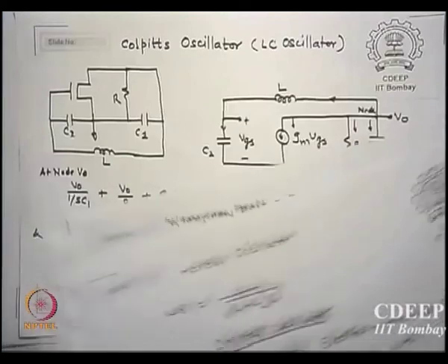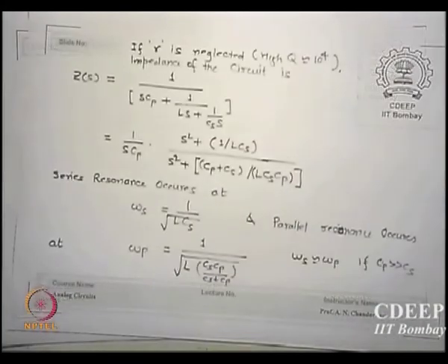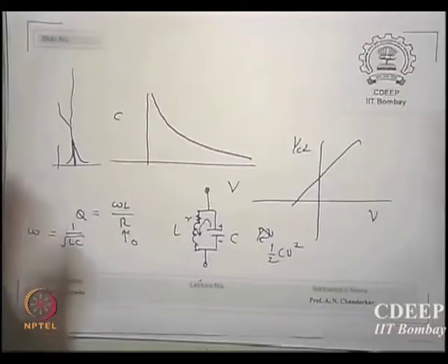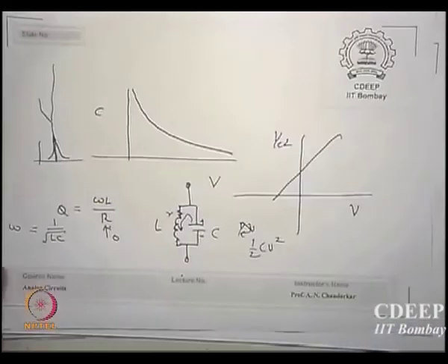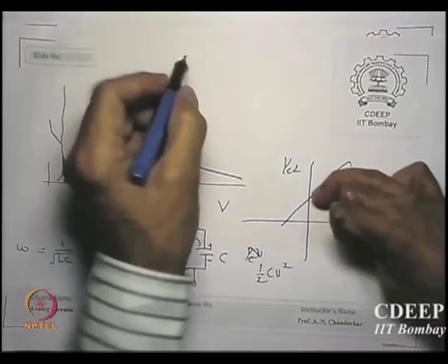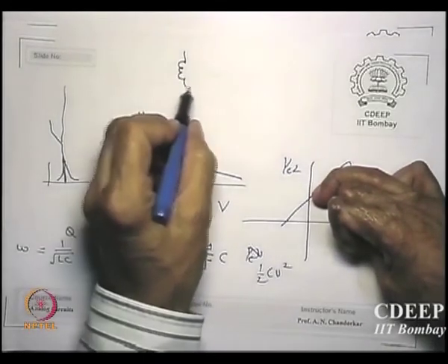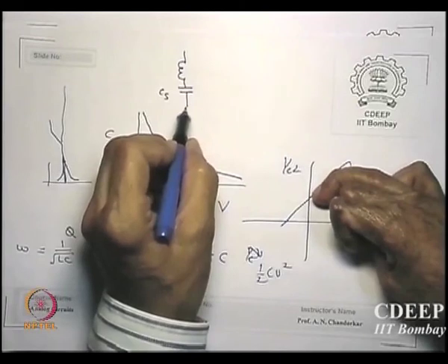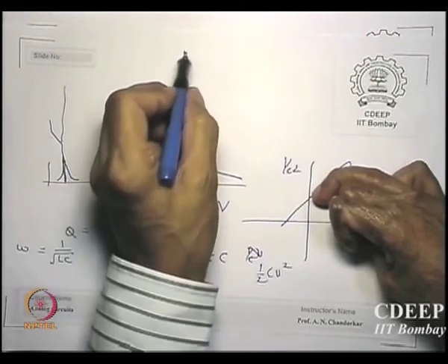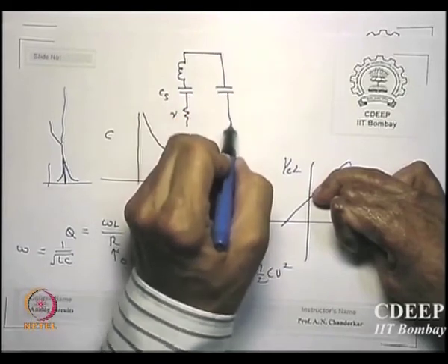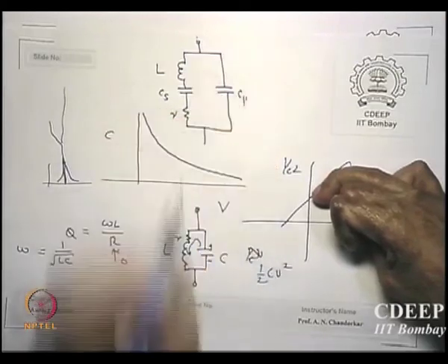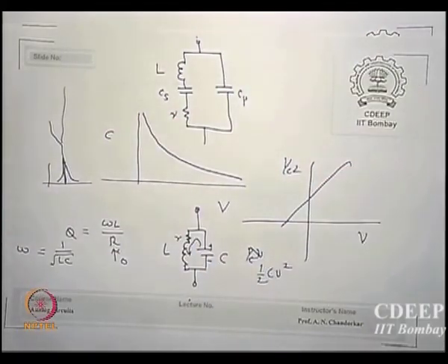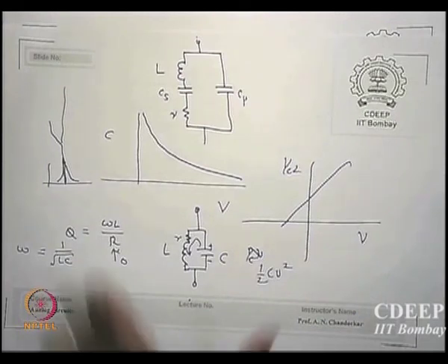Now funny part, the crystal oscillator which I am going to show you now does not really work the way we thought. Okay. Crystal oscillator is like a tank circuit. Okay. The only difference between this circuit and the equivalence is something different. It has an inductance, it has a series capacitance Cs, it has a small series resistance R, and it has a parallel capacitance Cp. L, Cs, Cp: this is the equivalent circuit of a crystal. Okay, I'll come back to it, but just to show you.